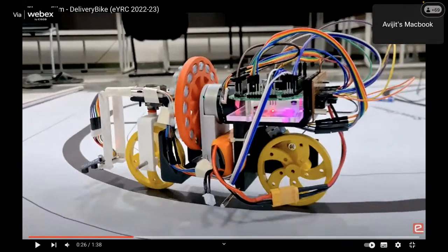Here you can see it is also a two-wheeled self-balancing robot, but the wheels are in front and behind of each other, and the balancing action is done using a reaction wheel. A reaction wheel is a flywheel mechanism which rotates clockwise and counterclockwise to provide the counter torque for keeping the system in the upright position, which is the unstable equilibrium position.